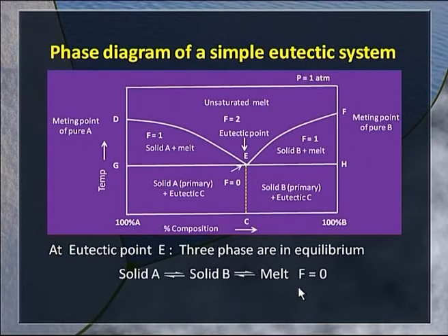When there are three phases, the system becomes invariant, because when there was one phase, it was a bivariant system, and when two phases are present, it is called a univariant system, and here it is an invariant system. So, at the point marked E, the number of degrees of freedom is 0, you have an invariant system on hand. That means the eutectic point represents an invariant point.